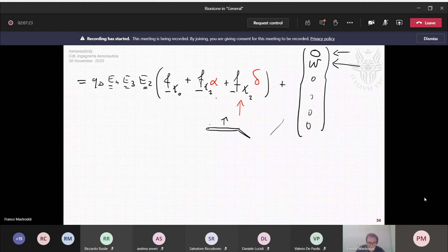When you have a normal in the body here, you have a normal also in the control surface, and if you have a delta angle of attack, you can represent this normal variation in terms of delta by this quantity, exactly in the same way you did for this vector here, delta Q1. So delta Q2 is just an extension of delta Q1 for representing the variation of the normal as given by the variation of the delta aileron, delta wingtip, tip surface angle of attack.